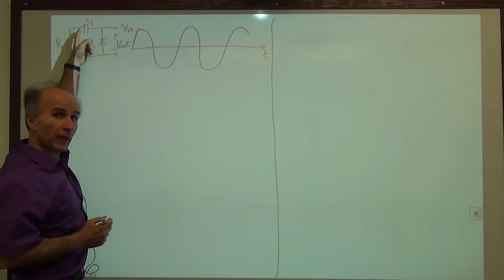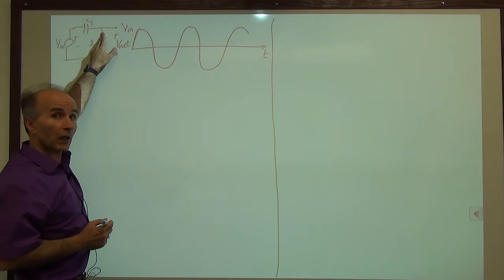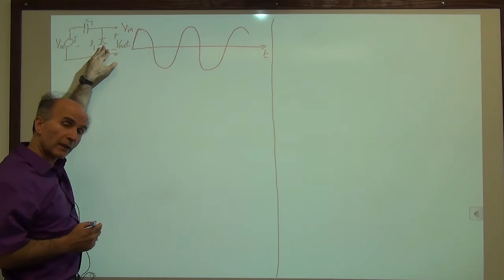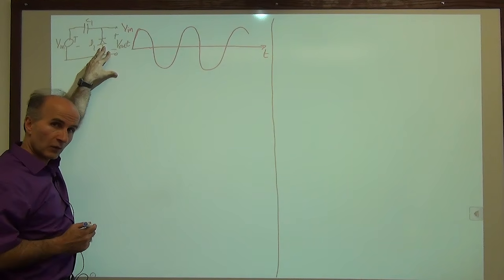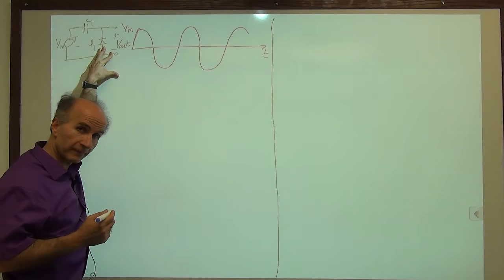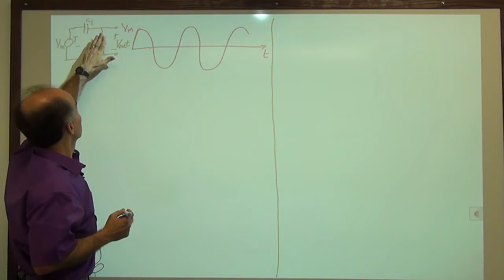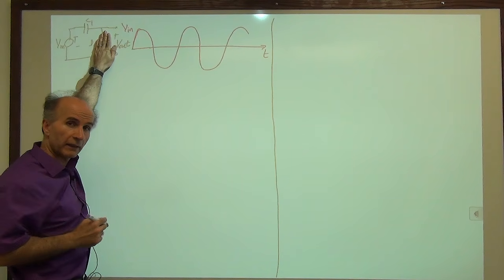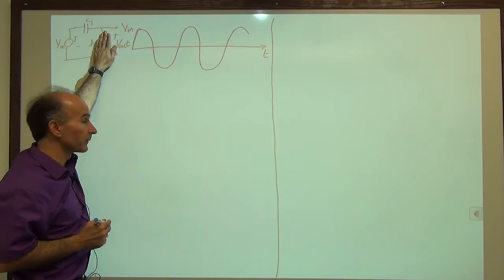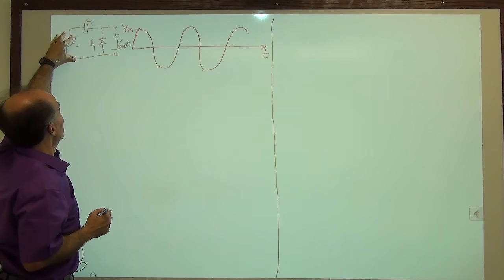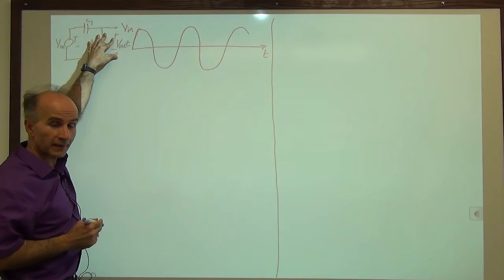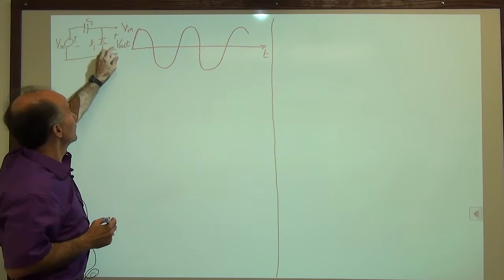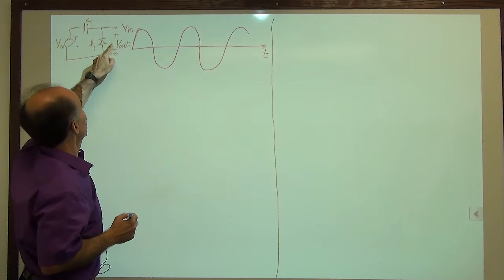So let's assume that the diode is off. If the diode is off, it is an open circuit. As we saw in our second observation, if the input changes, the output changes exactly like the input. Because the input is going up, the output will go up.